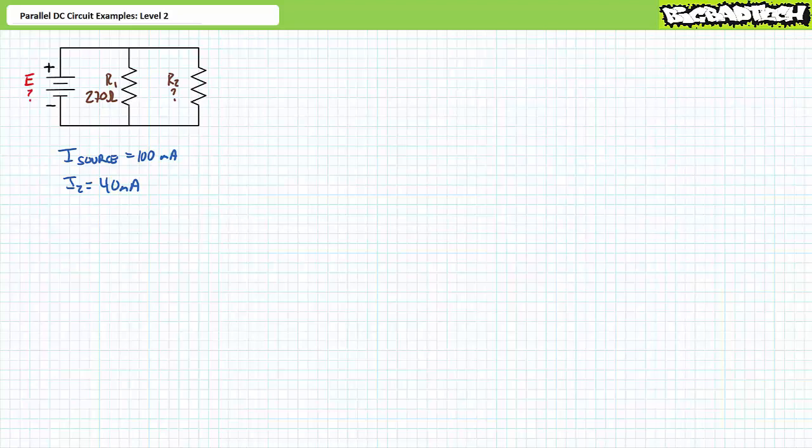My sincere advice for every single one of these scenarios is to lay out everything you do know about parallel circuits and apply these fundamental properties to the circuit in question. Ideally, you should be able to use the provided clues to make deductions about or to solve for other properties. You will no doubt recall that voltage across elements in parallel is the same. This is the most fundamental parallel circuit property.